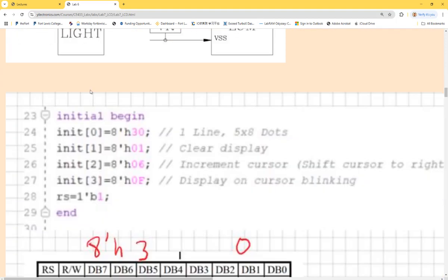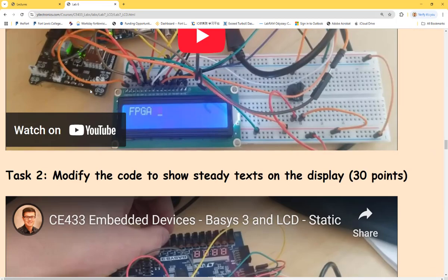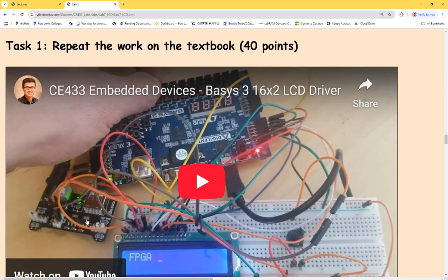And which one did we use? We use the Arduino little module here, this guy. So it has a 5 volts and 3.3 volts output, and you plug this into the adapter on the wall. The little adapter will convert that AC to 9 volts DC, and 9 volts DC will be regulated by the regulator on board, eventually giving you 5 volts. So the 5 volts is supplying power to this module. But keep in mind, including the FPGA and this power module and this guy, you have one common ground everywhere.